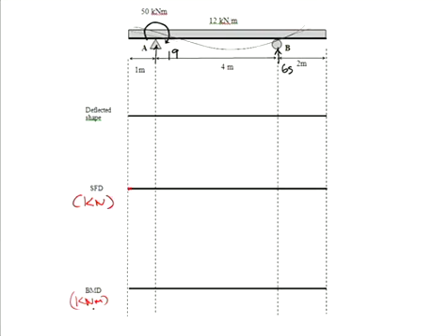Okay, we start at the left-hand end and we follow the load. And what is the load doing? It's reducing. It's negative. It's dropping by 12 kilonewton per metre every metre. So by the time I move across 1 metre, it has a value of 12. My reaction here is a total of 19, so I step up a value of 7. A bending moment does not affect the shear force diagram, so you don't worry about it. Now the load continues to drop by 12 kilonewtons per metre.